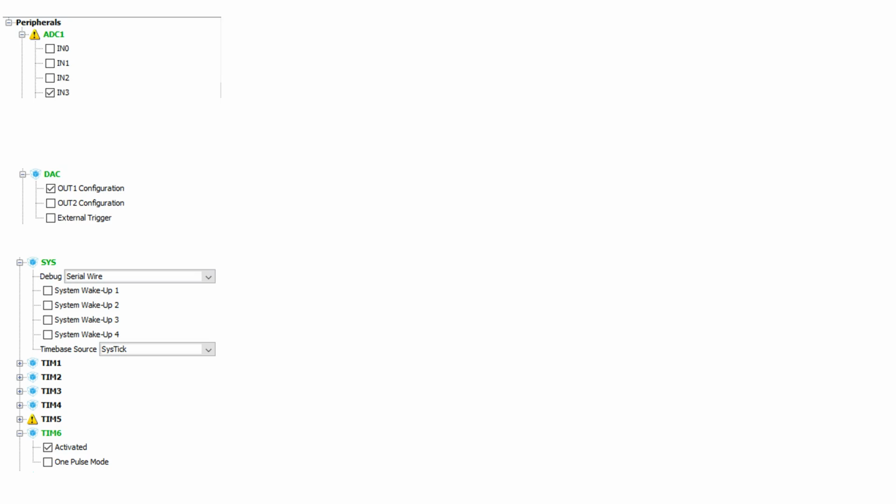The real reason is that timer 6 is a fairly simple generic timer. It's a 16-bit timer with limited functionality. The other timers, for example, timer 4, timer 2, can do a lot more, like PWM generation, input capture, output compare, one-shot, those kind of things. Timer 6 is fairly simple. It's a 16-bit timer. Activating it is fairly easy. You just click on activate there.